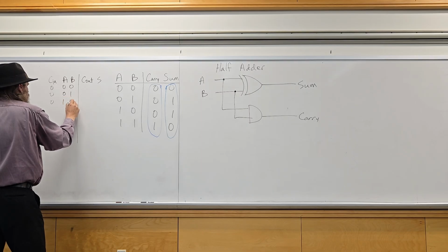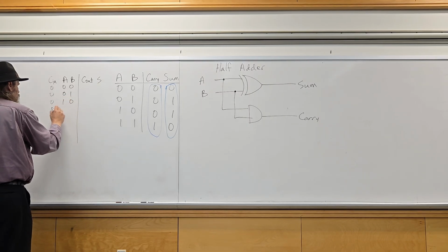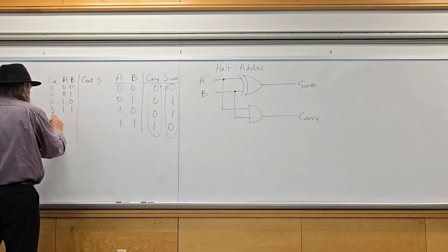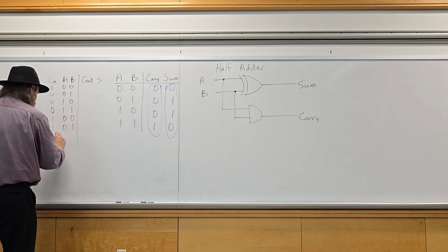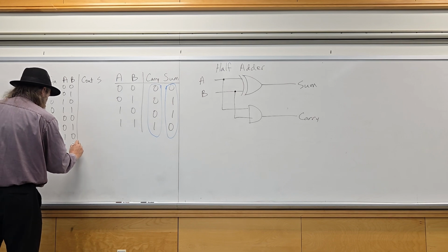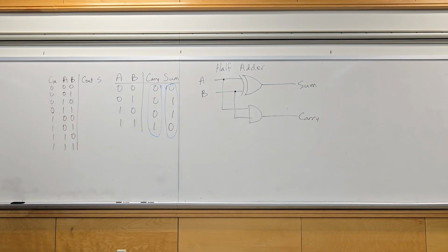And we'll do the state table real quick. All right, so you're adding 3 bits together. So the total is still going to be 2 bits, because adding 3 bits together, the largest number you can get is 3, right? 1 plus 1 plus 1 is 3. So that can be represented by 2 bits.